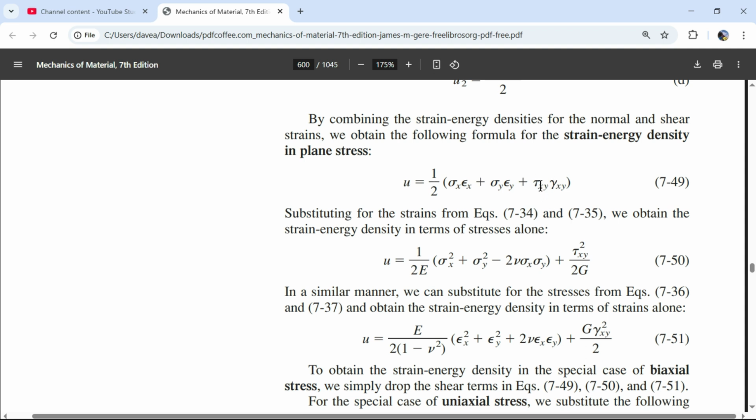And that's the more common one that I'm familiar with. Just like normal stress. Like 58,000 pounds is 29 million times 0.002. So normal stress is equal to E times epsilon. Sigma is equal to E epsilon. Normal stress is equal to modulus of elasticity times the strain. And so that's for normal strain. And then if you have shear strain, a very similar equation. Shear stress is equal to that constant times that small angle. So a pretty big number in pressure is equal to a constant times a very tiny number in angle.